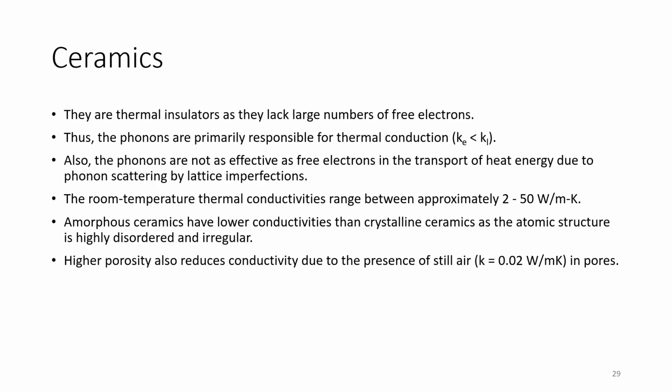Then ceramics are thermal insulators as they lack a large number of free electrons. Thus the phonons are primarily responsible for thermal conduction. Also, the phonons are not as effective as free electrons in the transport of heat energy due to phonon scattering by lattice imperfections. The room temperature thermal conductivities range between approximately 2 to 50 watts per meter Kelvin. Amorphous ceramics have lower conductivities compared to crystalline ceramics as the atomic structure is highly disordered and irregular. Higher porosity also reduces conductivity due to the presence of still air.